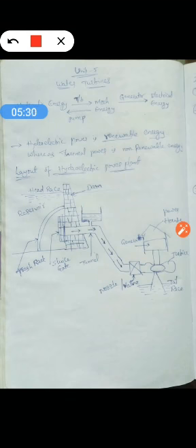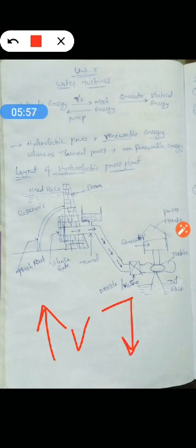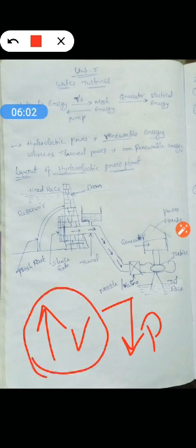And the next thing, nozzle. So nozzle is used to deliver the water from the penstock to the turbine, and we can also know the function of nozzle. That means it creates the high velocity of the water or fluid and simultaneously reduces the pressure of the water. So by increasing the velocity of water, we obtain kinetic energy, which is utilized in the turbine.